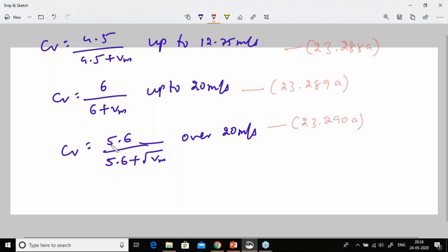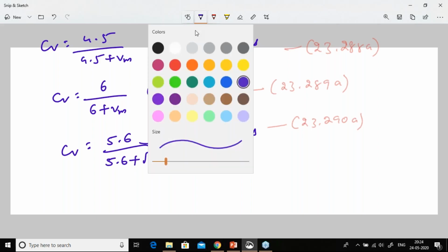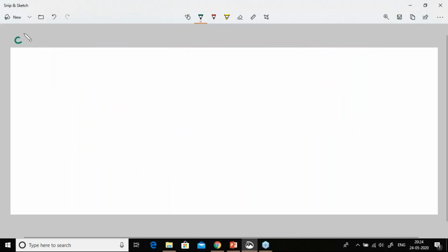By substituting all these values in the Ft equation, we will get some value for Ft. We have to call that equation number 2. By equating equation 1 and 2, we will get the module Mn by trial and error method. Once we get the Mn, we have to check for the stresses. The third sub-step, that is C, is check for the stress.